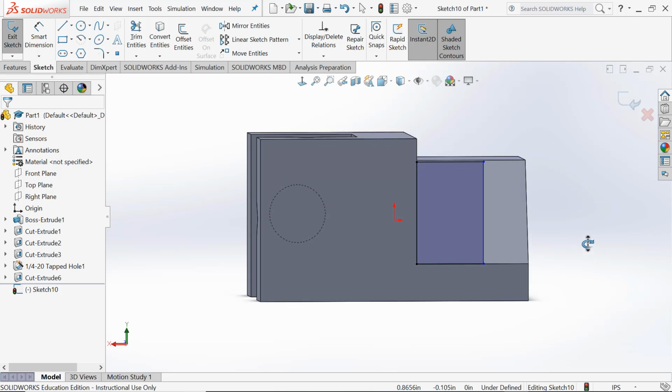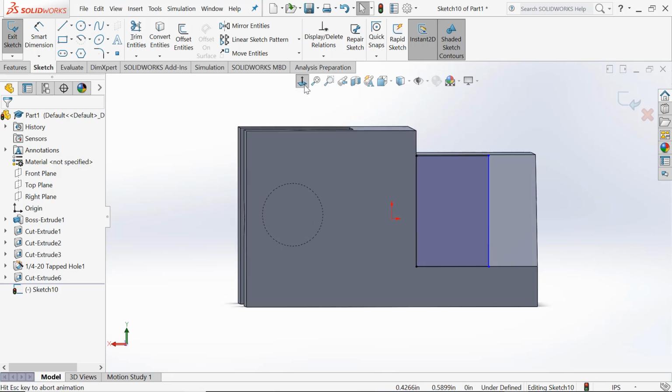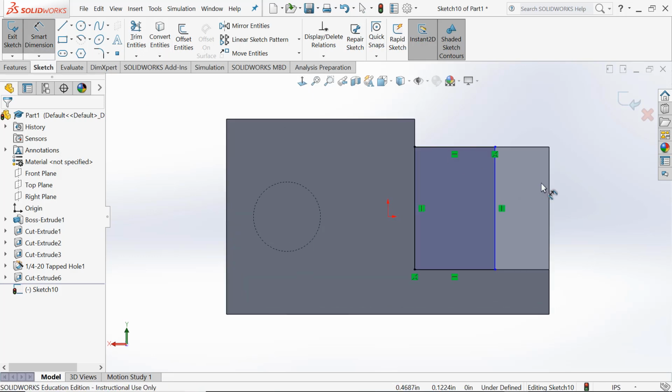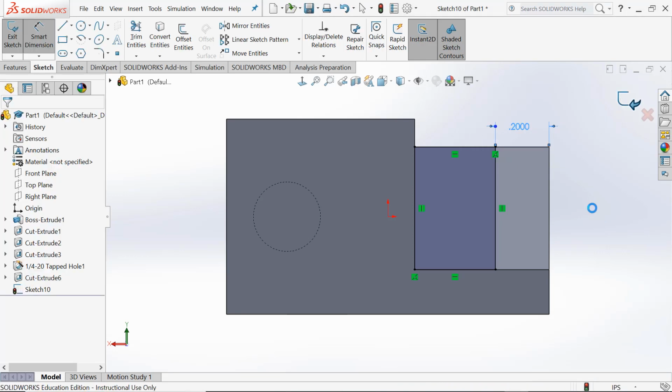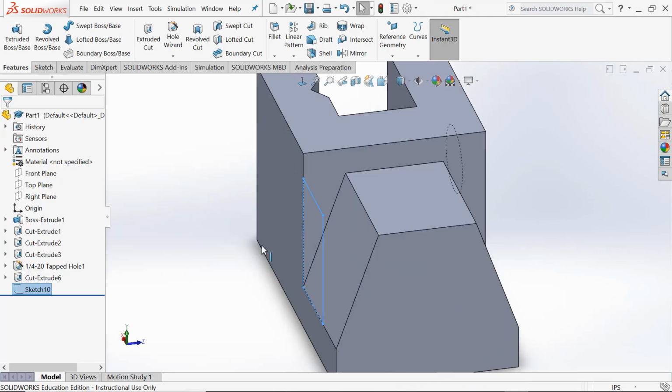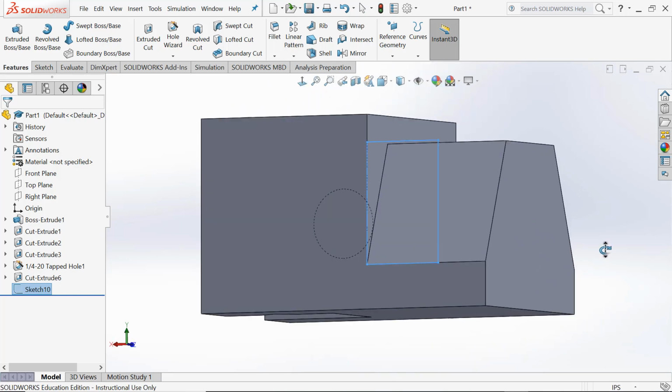And so when you go to make this sketch here, dimension maybe from here to here, I think it is, to make that cut, whatever it might be, you don't really have to draw it on this face. In fact, if you draw it on this face, you'll have a problem because it'll try to cut perpendicular to that face and slice your part in a really weird way.